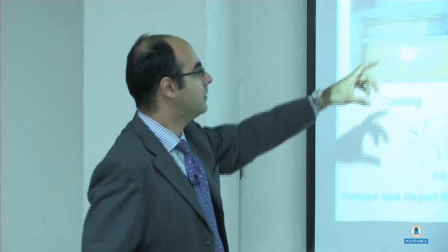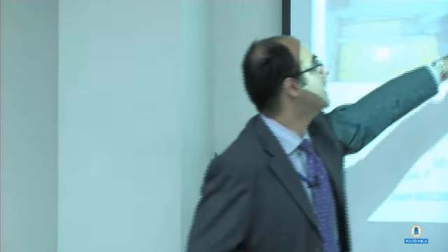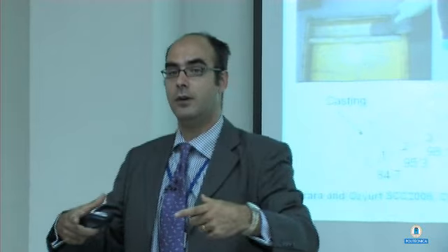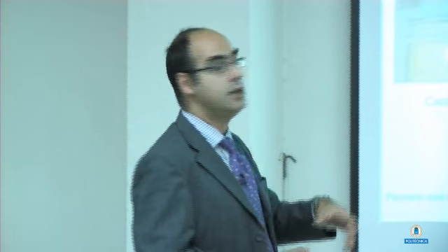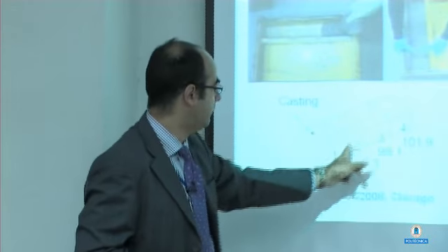Basically, we optimized the rheology of the paste, of the mortar, and of the fiber reinforced mortar with very simple tests, the mini-cone slump flow and the Marsh cone tests. And after that, we also checked, with reference to small scale specimens, what we call the fiber dispersing ability. For example, from the patty of the mini-cone flow test, we divided it into sectors, and after that washed the fibers and weighed them, and checked how many fibers were in the center and how many fibers were in the outer ring, because that was an indicator of the tendency of fibers to settle down. Or we simply cast a small beam here, and after that divided it into 4 sectors and checked the weight of fibers in each one.